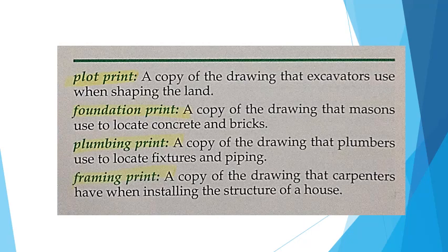The electrical print is used to order the equipment, determine the length of the cables and wires needed, and inform the local inspector about the proposed layout. Since this print is usually created directly from the floor plan, you can foresee most of the structure and adjust the cable and conduit routing.